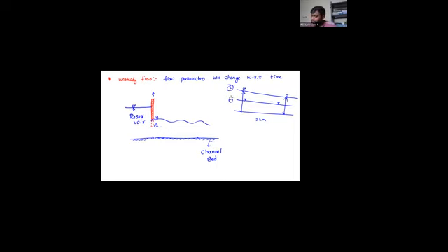This is A. Before lifting of the gate, flow is uniform. And this is B. After lifting of the gate, do you think everywhere over a 1 kilometer length the water level will rise by the same amount? No, it is not at all going to happen. Keep that in your mind. Uniform flow will not be possible under the unsteady case. If I say uniform flow, that is a steady uniform flow only, and unsteady uniform flow will not be possible.